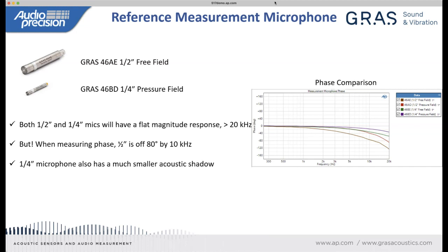And I'm going to do this by what I might call the simultaneous substitution technique, in that I physically placed the measurement microphone quite close to the microphones under test, so they're sort of sharing a sound field. And that does influence the selection of measurement microphone that I would use.